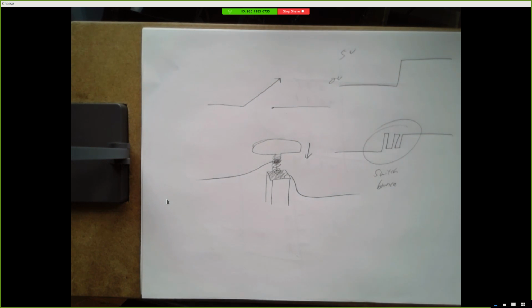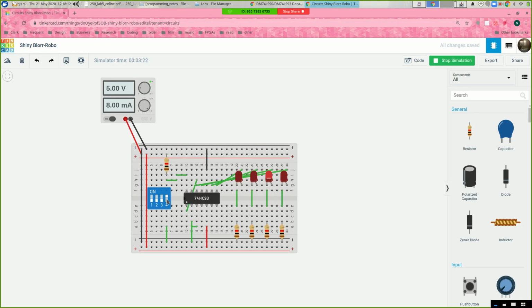And if you were to build this circuit in the lab and flip the dip switch, you would actually see that it registers more than one pulse. Could be 2 or 3 or even more. Okay, so I think that's what we're seeing here. But let's go ahead and build a circuit from experiment 1, which will generate pulses without any of these noisy glitches. Okay, and let's see what we get from that.